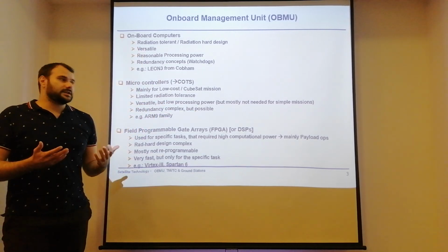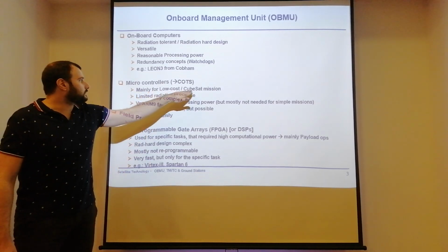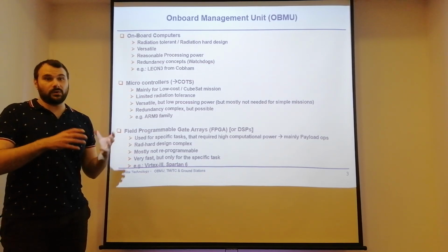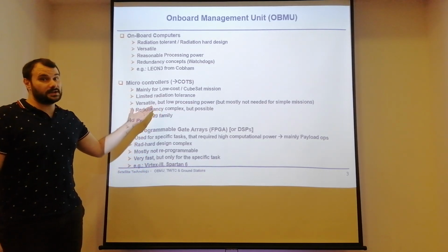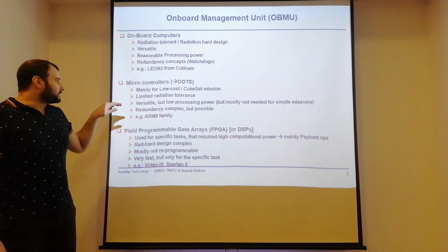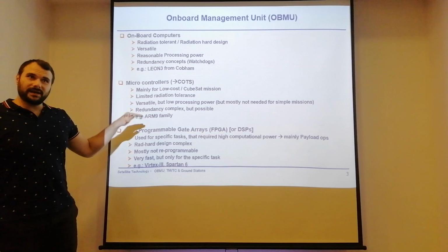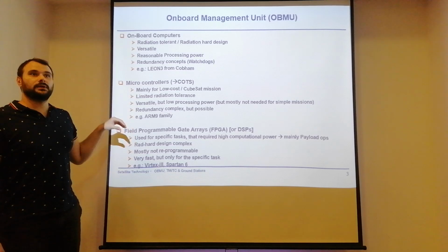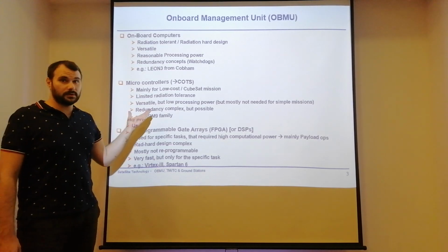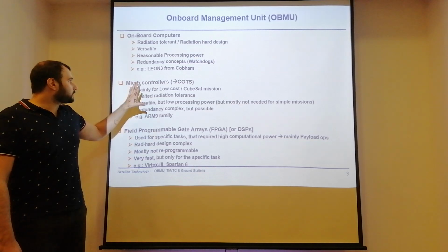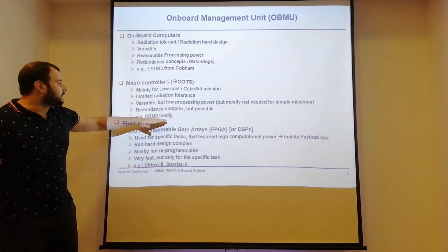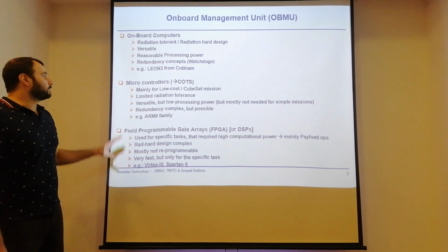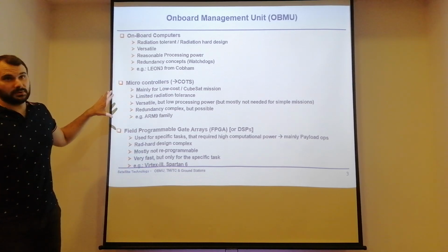However, usually that is not really necessary. As we said, we're mainly going to use it for low-cost and CubeSat missions, where you only require limited onboard processing power anyways. So this is not a big problem, and you save a lot of costs at that point. Redundancy concepts are quite complex for these, but it is possible. There are missions that have shown a really good redundancy concept. And just to conclude here, a very commonly used microcontroller is some of the ARM9 family to control as an onboard management unit.